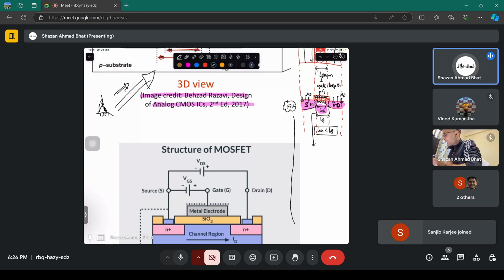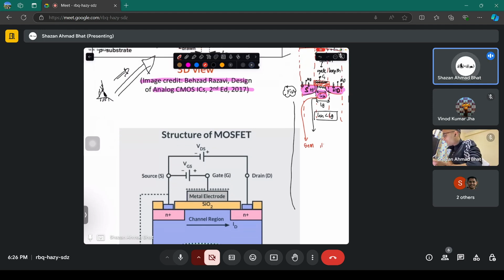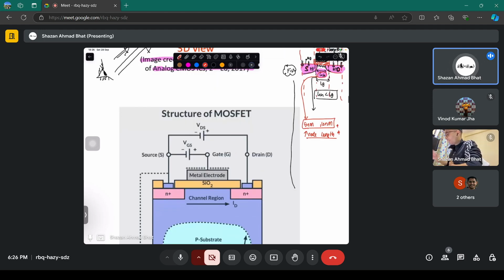So this is that particular channel length which those marketing agencies talk about. They talk about, let's say, 5 nanometer or 10 nanometer channel. Basically, it does not necessarily mean that the distance between source and drain is 10 nanometer or 5 nanometer. It's a different strategy. What they give you is something called node length or node. It's a different concept. Let's leave it, let's not think about it.